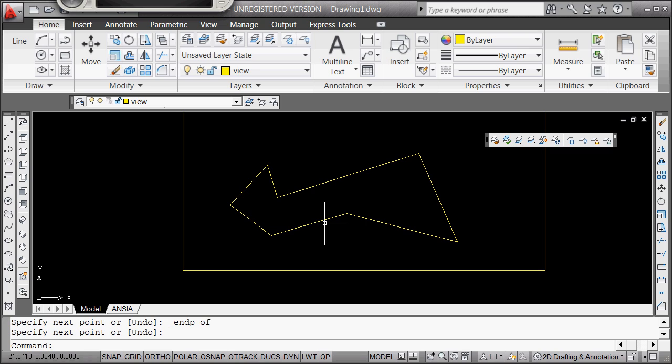Here's what we did. We drafted the first line by direction using the command line and then at, distance, less than, angle. From there we used the grips, turning interior angles. We left clicked on something, we left clicked on the grip, and then we used the space bar to go through till we got to rotate. We said C for copy, we gave its rotation angle, and then we changed the length of the new thing by either the length command or by drawing a circle and trimming, or there'll be other methods.